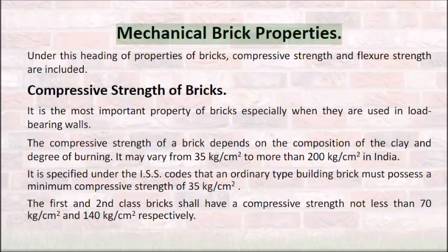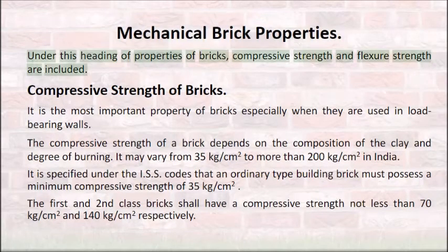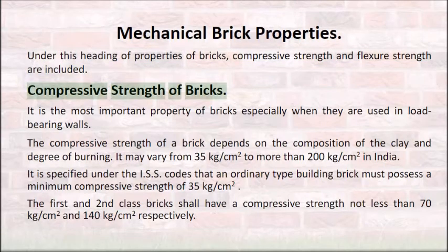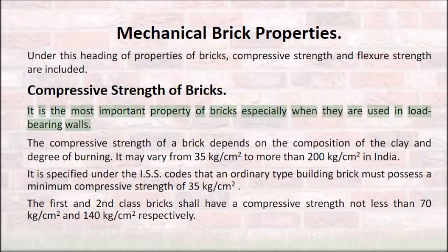Mechanical brick properties. Under this heading of properties of bricks, compressive strength and flexure strength are included. Compressive strength of bricks is the most important property of bricks, especially when they are used in load-bearing walls.